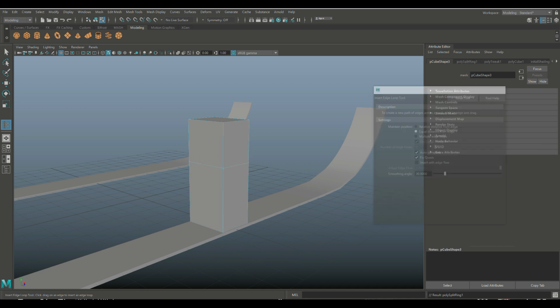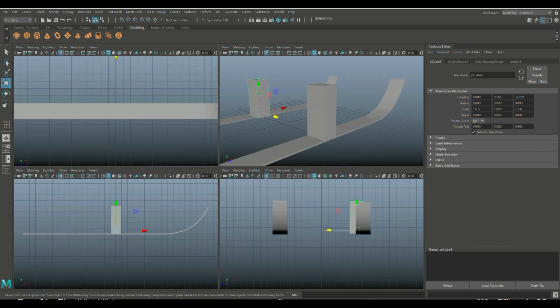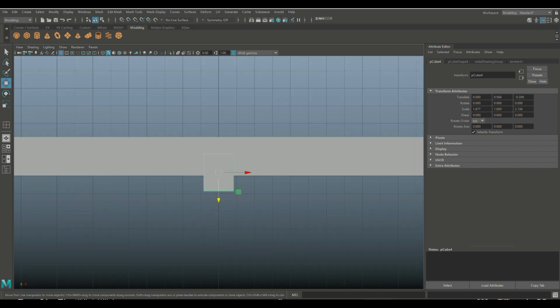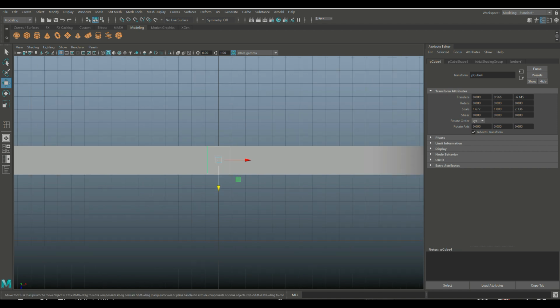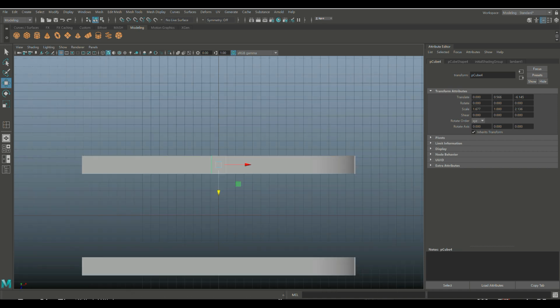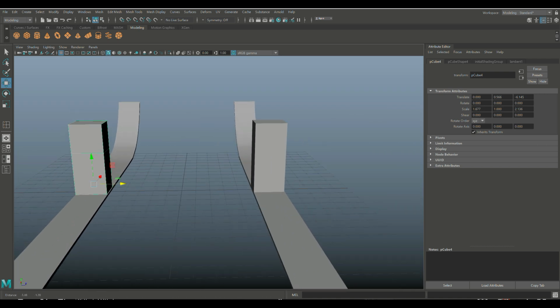Okay, close that, Q on the keyboard, copy this guy, Control D to duplicate, W to move over. After frame, push that in here as before. And we're going to need two of those, right? Or two sets. But let me complete the bridge first, all right? So I got one, I got two. Let's go to Mesh and Combine, right?